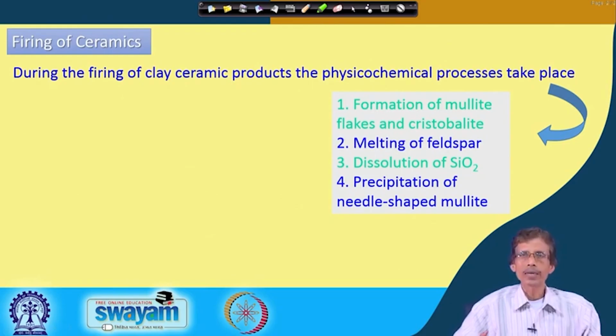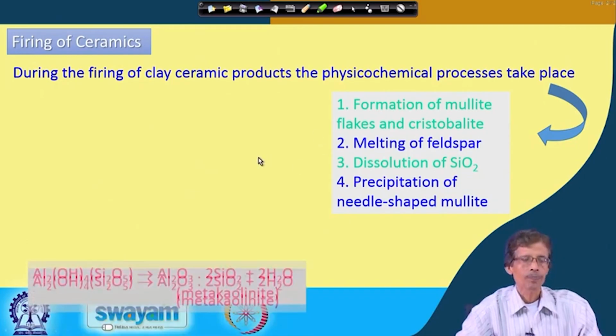The way we know that when a saturated solution is there at high temperature, if you allow it to come to room temperature, or if we cool it down to room temperature, the extra material, which is not allowed by the sufficient solubility at that particular temperature, we get back as the excess solid amount in the form of small crystals. This is the basic fundamental theory behind the crystallization process. So, similarly with the temperature variation in the molten state also, whatever is generated out of this step is your needle shaped mullite material.